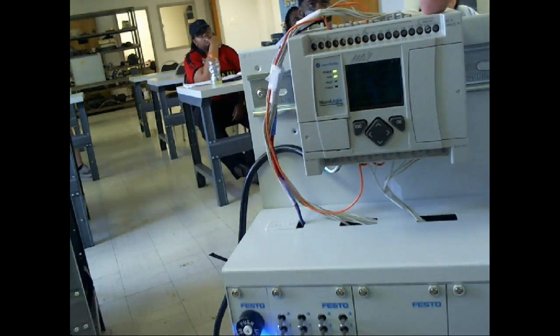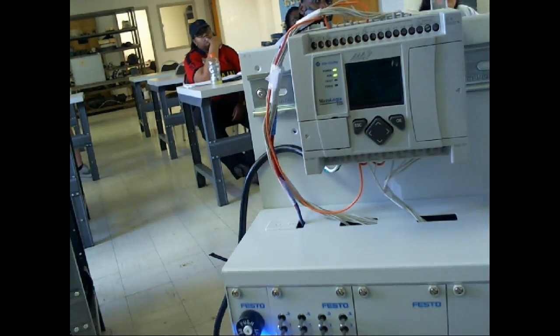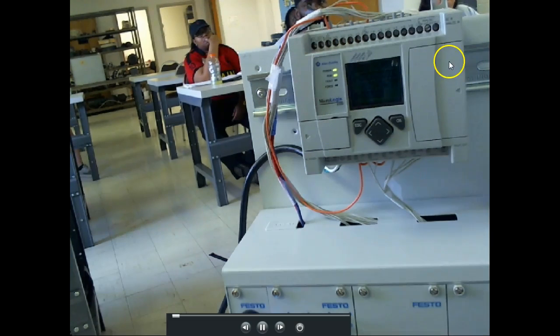And then the analog inputs, which are right here, these run off 10 volts. So you can't use this power supply to run these analog devices. So you'll definitely have to have an external power supply to run those, or do some tricky stuff. Are we okay? So that's the way we wire these things up.